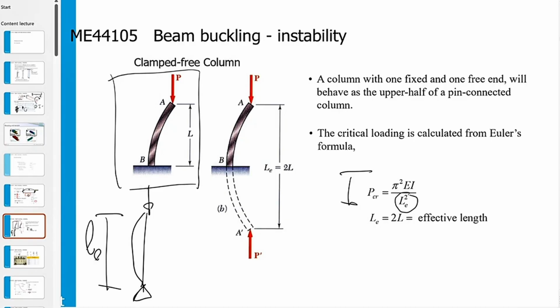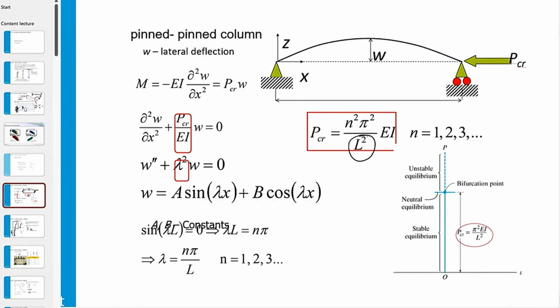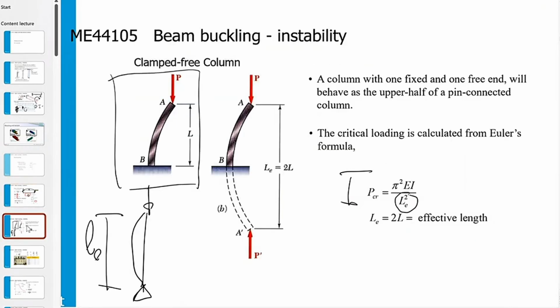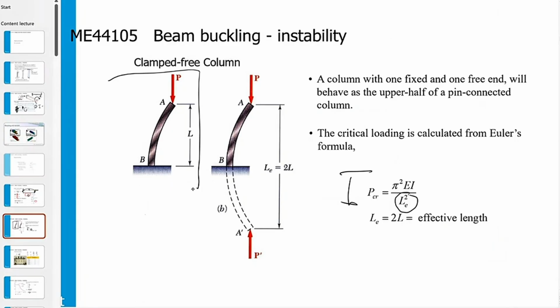But if we use different constraints, we can have a different value. And of course we can calculate it with the formulas and use the right boundary conditions. So here it's clamped and there it's free. But it is much faster if we look at the shape of the buckling mode. What you see here is that in reality the buckling shape has a symmetry plane here, so the real buckling shape is twice the length of the beam element.